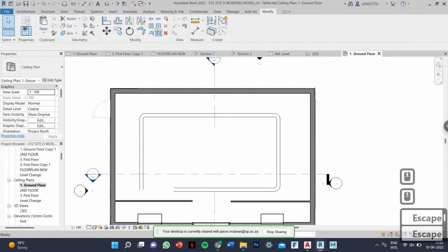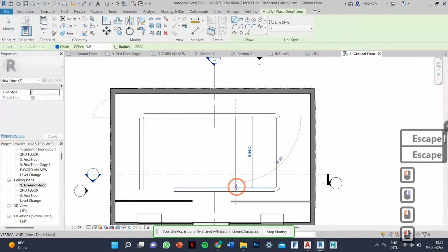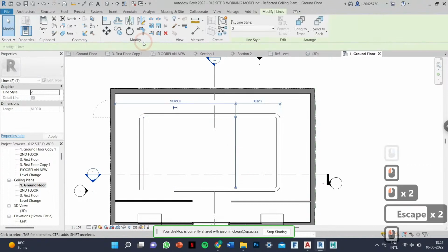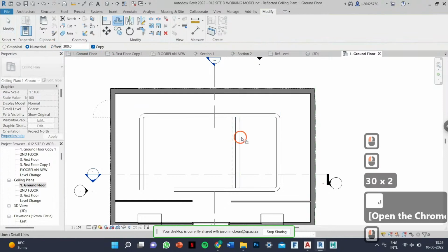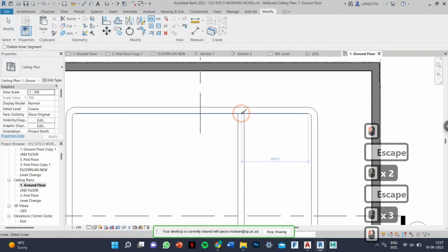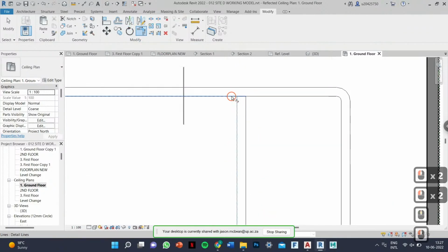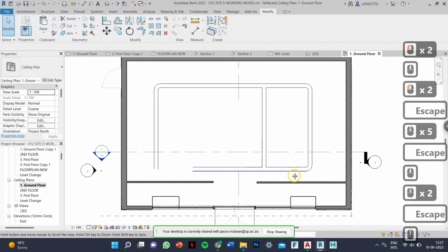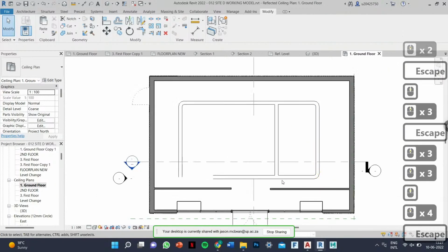If there's a new duct, there's a branch that goes down here. Click on this, right click, create similar. Now going to layers. Select this line, offset, 300. Split line tool. So split this up, split line tool. Voila. Voila. Trim. Trim tool. Way more intuitive than AutoCAD. Check that out. That's a duct. Then you can show these little things here in groups again. You can make a group. But there's your aircon duct.